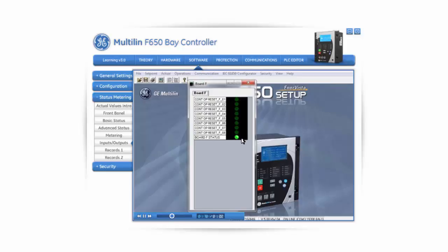the signal is active. As a reminder, recall that contact inputs or outputs are physical signals on the relay, meaning they represent a literal contact that opens and closes. A virtual input or output is an internal state of the relay, often the solution of an equation. And finally, remote inputs or outputs are a way of exchanging digital state information between Ethernet network devices and therefore are similar to virtual signals.